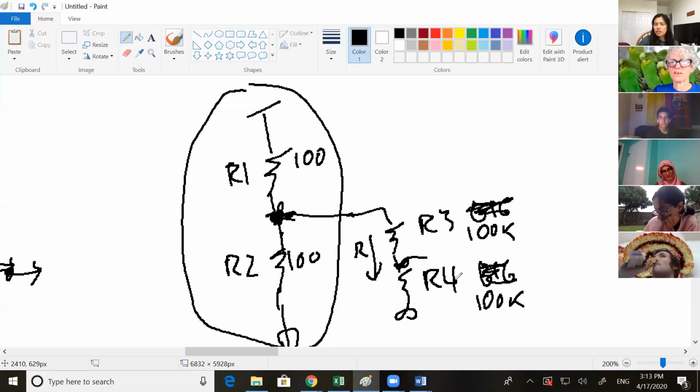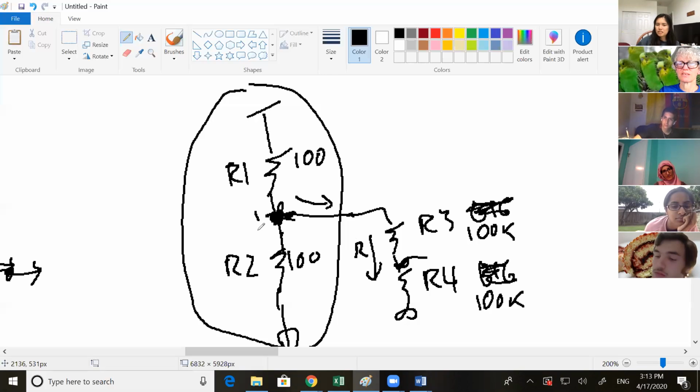Okay. So to make it better, you would make the R1 and R2 smaller? Or bigger, so that they don't go through? Well, if you make this bigger, then the current's going to want to split again. So rather than making R3 and R4 big, you want to make R1 and R2 small. That's a solution that works.